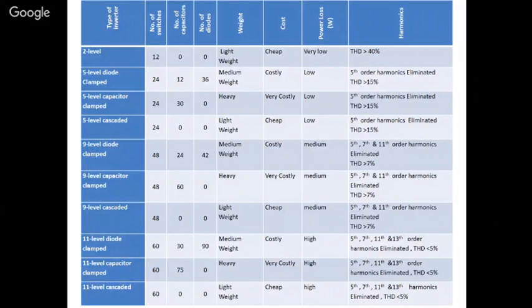Here each and every DC you are using should be isolated. It is not like you convert AC to DC, rectify it and take multiple DC from that. You should not do that. In the case of 11 level, for single phase you require 5 DC sources. For 3-phase, 15 sources, and all these 15 should be separate sources. Whenever you erect PV panels, it will not come as a single big panel. Why? If a small portion is shaded, the whole system is disturbed. So mostly you would have seen that they keep different modules, so you have more DC sources.